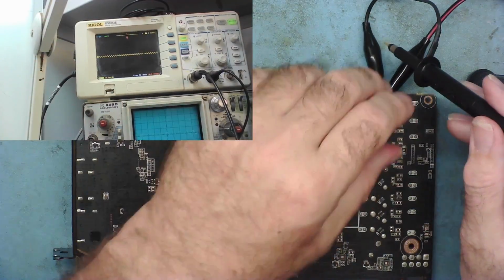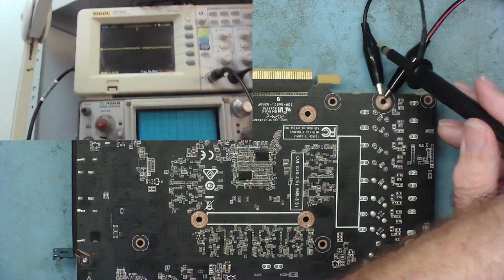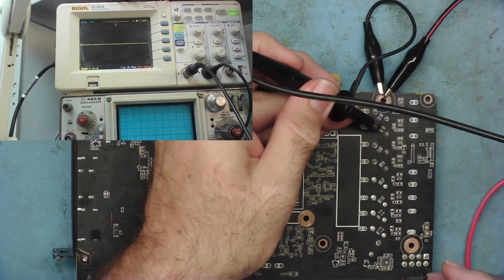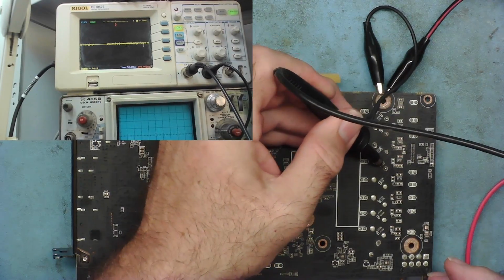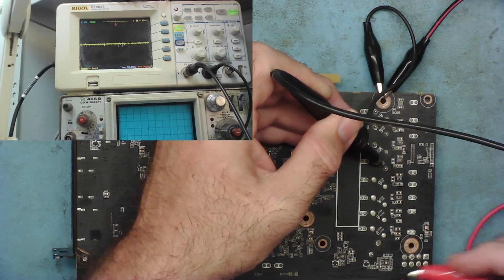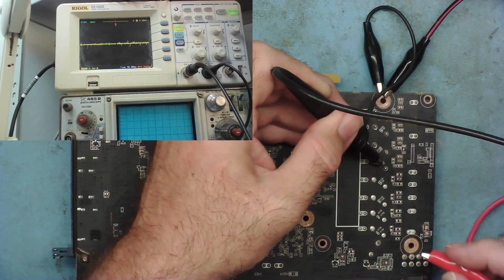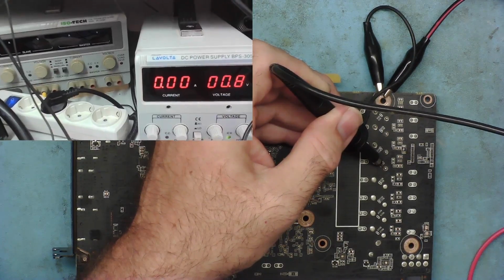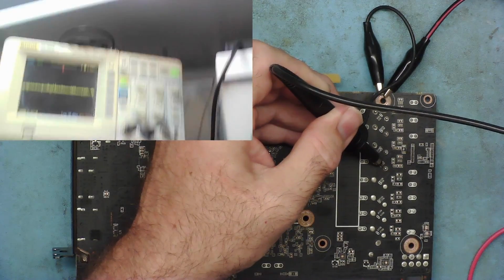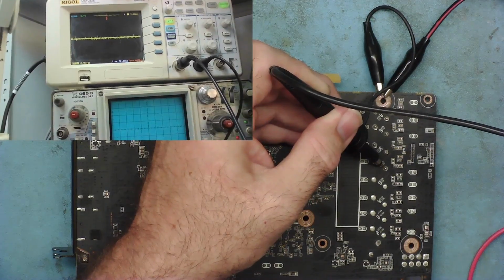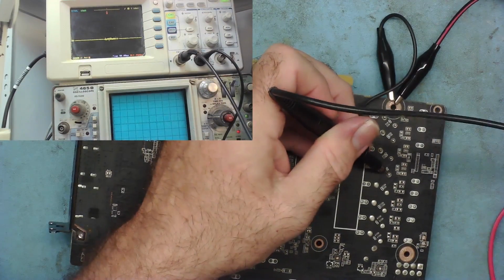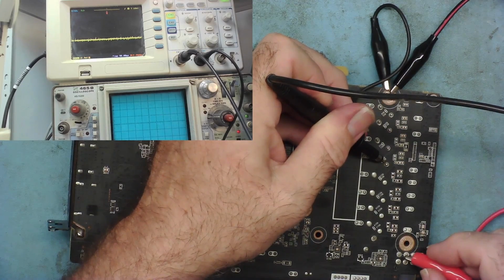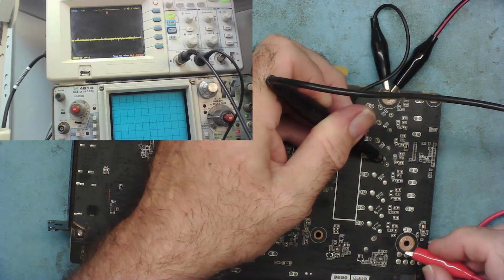So with this method, I have my digital oscilloscope set up there. I'm going to put the scope probe on the coil. So we'll start with this one. And I'm now going to touch the power in to the 12 volts. The power supply is set to 0.8 of a volt, maximum current, so it can't do any harm to anything. So I'm on the first coil, and let me very briefly just touch the connection.